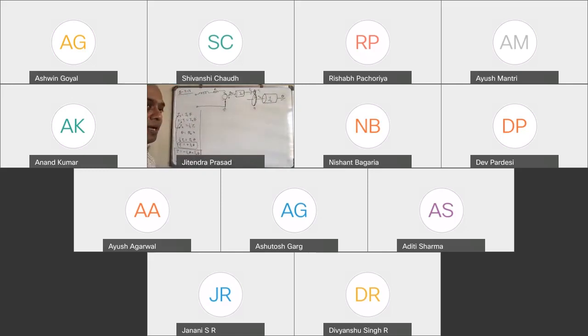What I would recommend is always draw the free body diagram. All the forces you see there, automatically you will know what you have to do. It makes sense that whatever torque is here has to drive both of them, this also and this also, and hence this equation, J_L and J both should be there, and hence you have that.